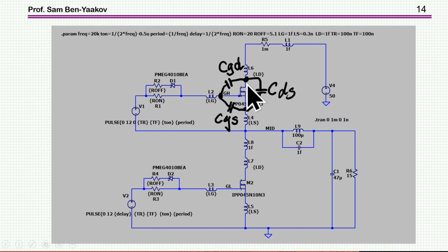So we have here an oscillator that you can actually analyze depending on the values of these elements, and this actually oscillates during this transition, and the oscillation, of course, will be a function of the inductances that you have in the circuit. And as it turns out, this becomes very important because you have feedback to the gate, okay? So the voltage across this inductance is being fed back, so the whole thing is starting to oscillate.